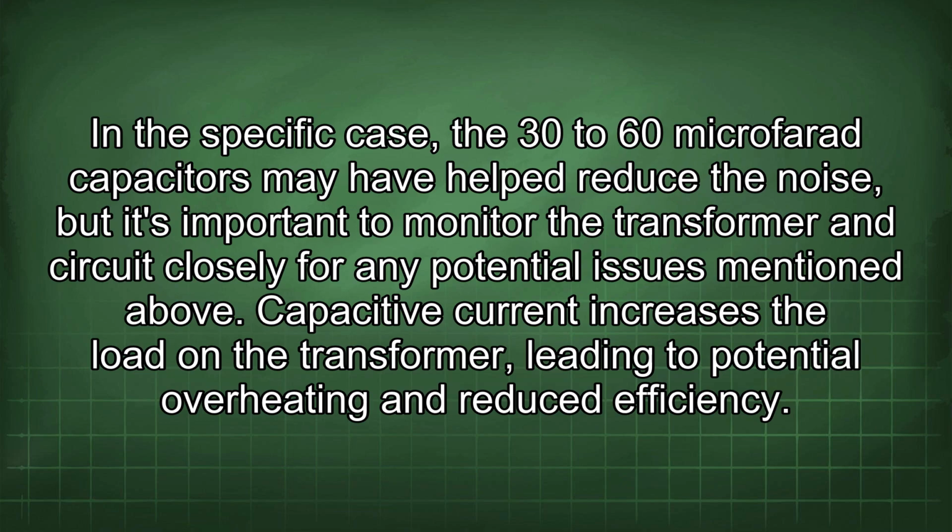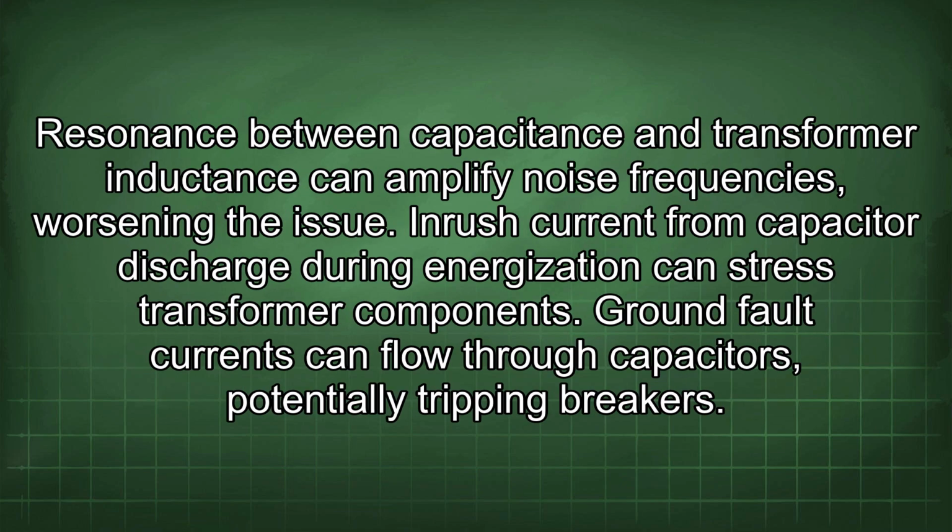Capacitive current increases the load on the transformer, leading to potential overheating and reduced efficiency. Resonance between capacitance and transformer inductance can amplify noise frequencies, worsening the issue. Inrush current from capacitor discharge during energization can stress transformer components.